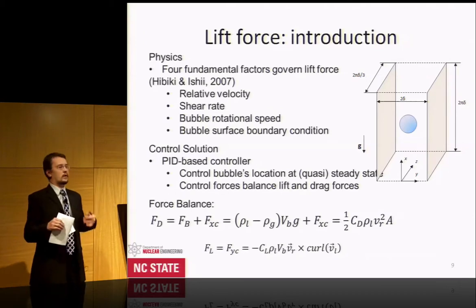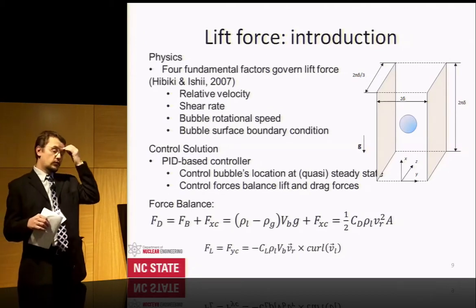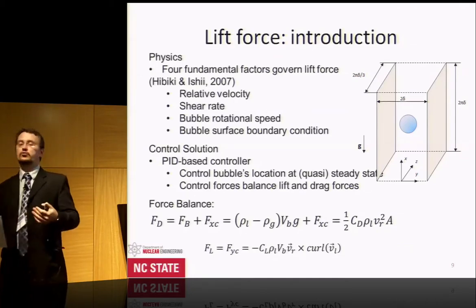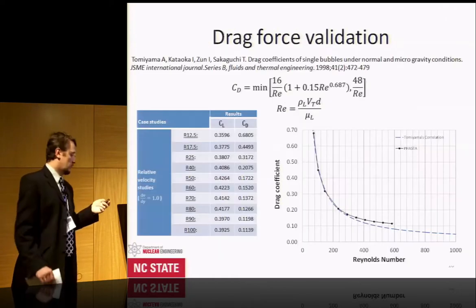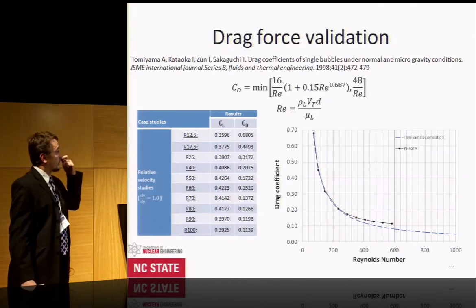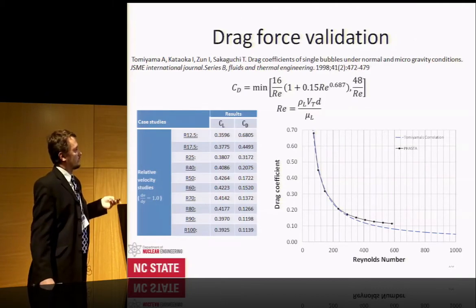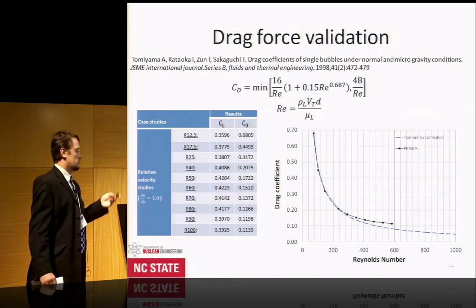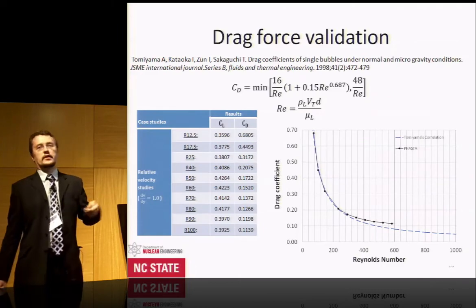And this physics is very important to provide closure laws for the modeling approaches, which use much coarser meshes when you cannot resolve the bubbles, but you have to supply the models with what kind of forces are acting on that bubble. And we did some validation: our method works pretty well for the drag force against experimental data, and there is some explanation for that, because the bubble deforms, and we experience a little bit more drag than